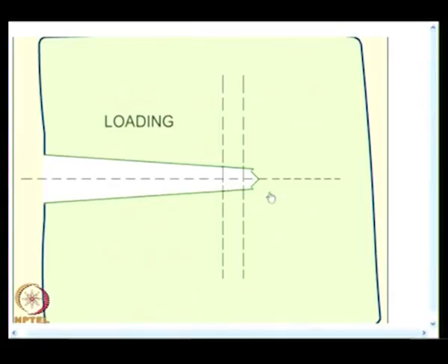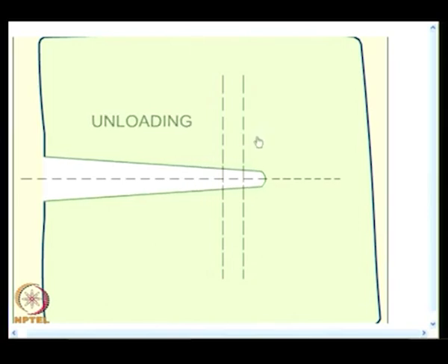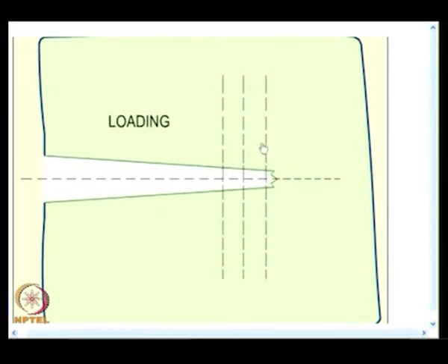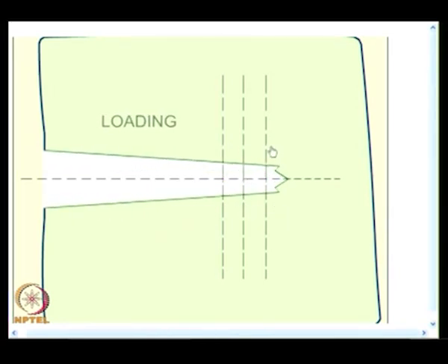The whole process starts all over again, and what is also attempted to show here is that the delta a you come across after each cycle would be slightly different. After several cycles, because the crack is growing larger, stresses also will be very high. So, the increment also will become larger and larger as the crack grows. This is easy for you to extrapolate. In fact, in one of the assignment sheets, you will go and find out crack growth rate by processing the micrographs.